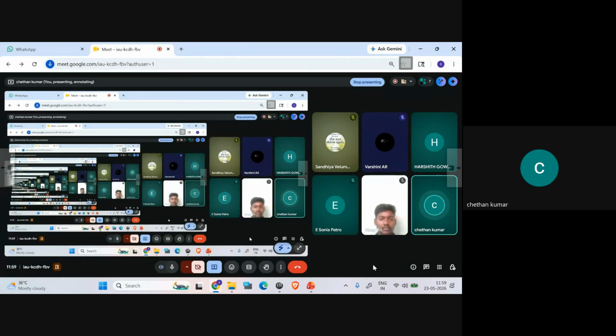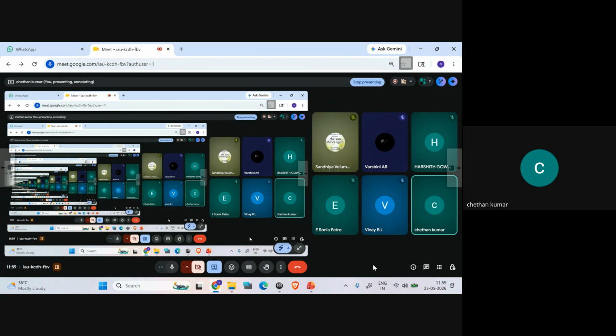That is the pre-silicon stage. Post-silicon stage means in the lab, the chip undergoes different conditions. They physically increase and decrease the temperature, and they physically increase and decrease the pressure. In the same way, they subject the chip to all these physical conditions in the lab in post-silicon validation, once the chip is completely manufactured. But in pre-silicon, by using software tools, they analyze everything.